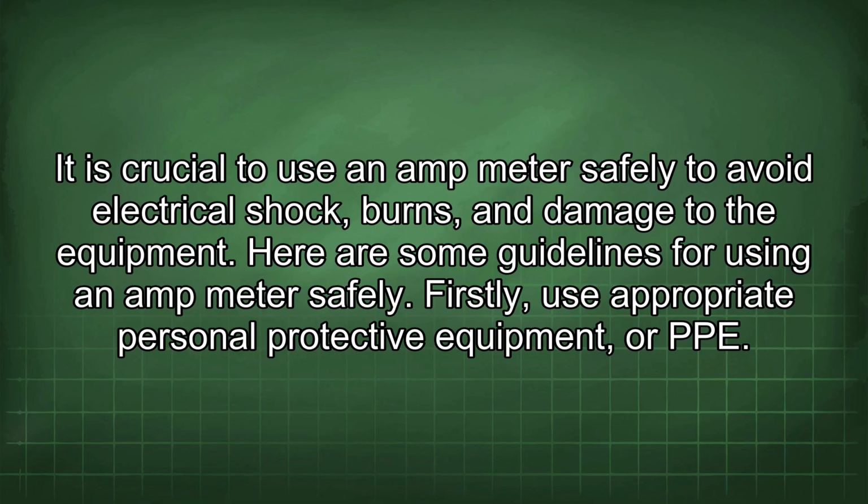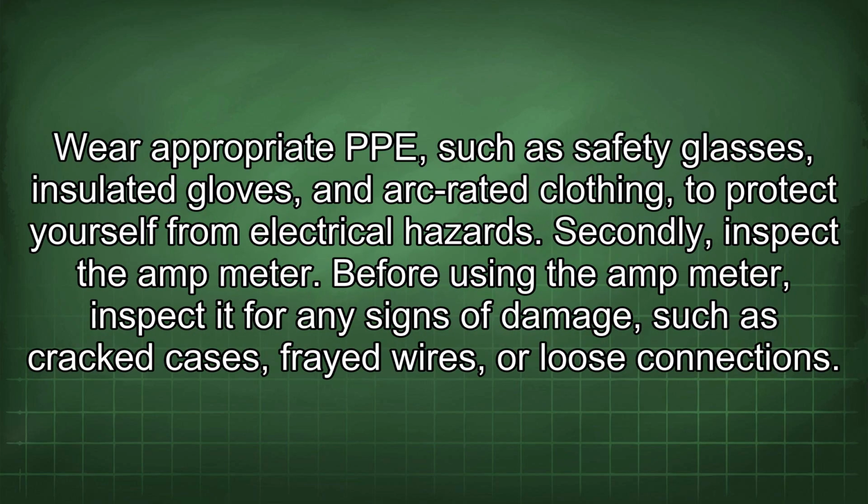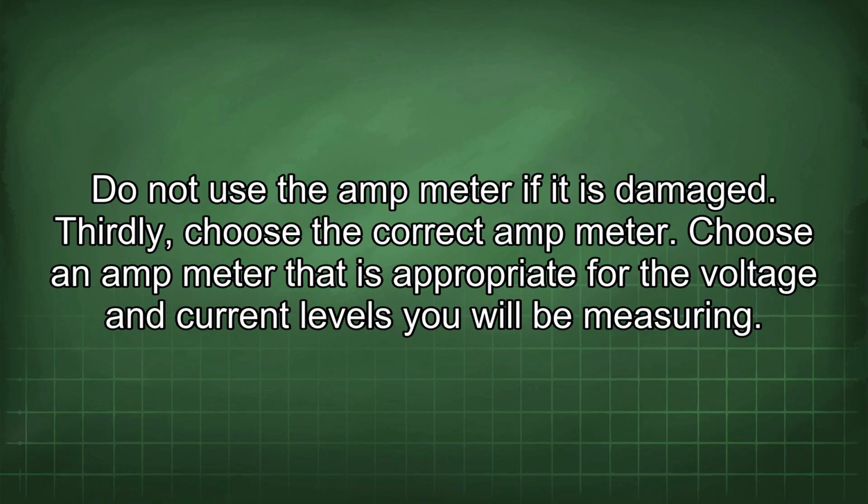Firstly, use appropriate personal protective equipment, or PPE. Wear appropriate PPE such as safety glasses, insulated gloves, and arc-rated clothing to protect yourself from electrical hazards. Secondly, inspect the amp meter. Before using the amp meter, inspect it for any signs of damage such as cracked cases, frayed wires, or loose connections. Do not use the amp meter if it is damaged.